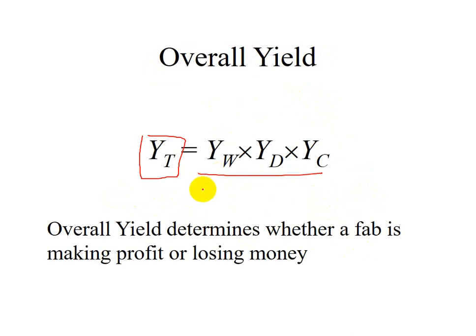That wafer yield is basically depend mainly on processing and wafer handling. Careless human handling and the robot malfunction or miscalibration can break the brittle silicon wafer. A faulty process such as misaligned photolithography followed with etch or ion implantation, wrong dopant concentration, poor uniformity, or large amount of particle on wafer, etc., can also ruin the wafers.